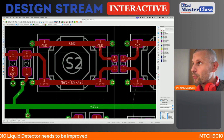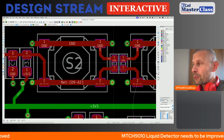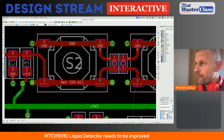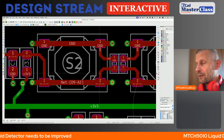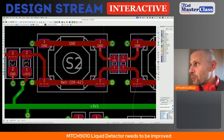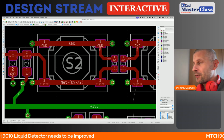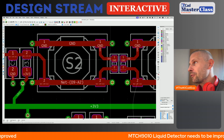Ideally, there should be a via close to the ground pad, because if you imagine the charge going through the space between this track and the bottom layer reference plane, the energy goes through the diode and here in between the top and bottom layer, in the space of the PCB.